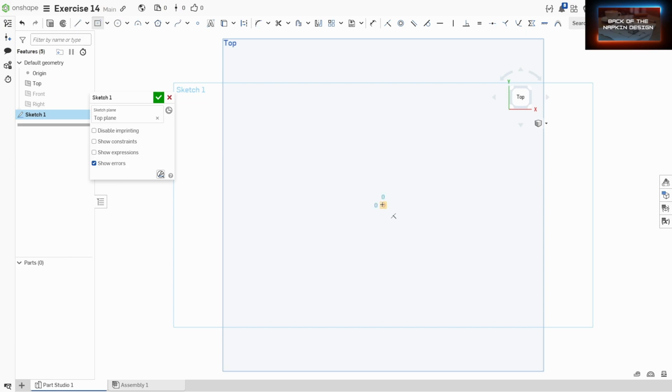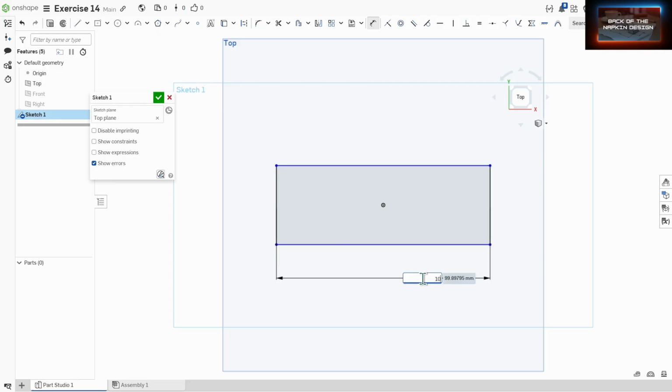Click on this guy right here, and we're going to go 100 millimeters wide. We can go just approximately, and then we've got to go 135 tall. There we go. Let's hit D for dimension. Let's dimension this guy. Here to here is 100. Enter. Here to here is the 135. Okay, sometimes it does that. Control Z to get back out of that. D for dimension to get back, and then click here to here, and then 135, enter.